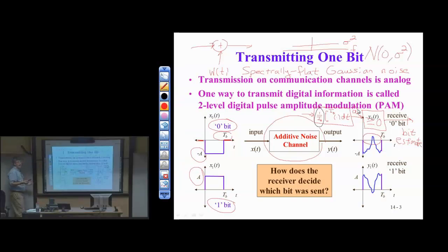I'm just doing 1 bit here; we'll do 2 bits in a second. So I want to repeat this over and over again, every symbol period, or in this case every bit period, and get the average value over that interval. I assume that's my estimate of whether I was positive or negative. But really what it is, it's an estimate of the symbol amplitude.